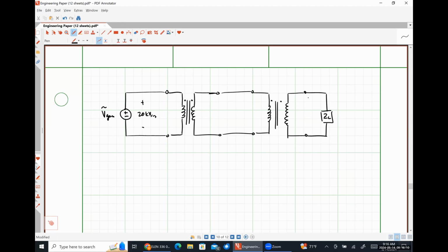This is a very simplified representation. In our homes, we would have a magnitude of around 240 volts RMS. We split that 240 into plus and minus 120, which is what we get on our outlets, but that's another bag of cats. That's just a center tapped transformer type thing. So we have the generation side on the left, distribution on the right, and in the middle is transmission, or how we transmit power over long distances.